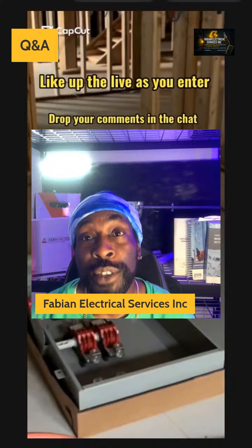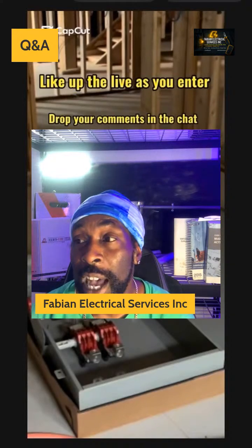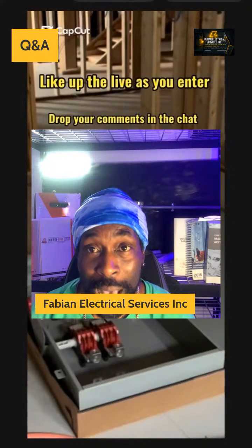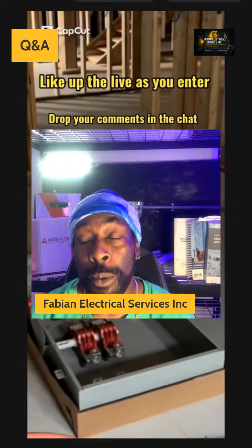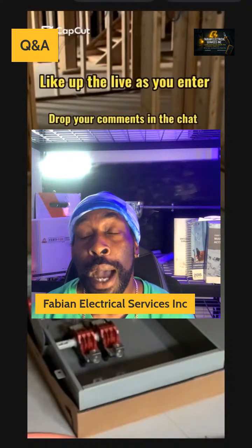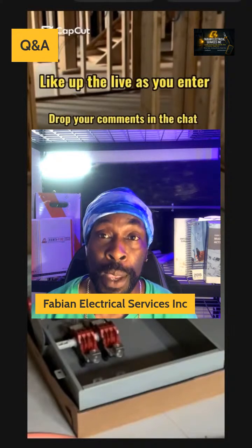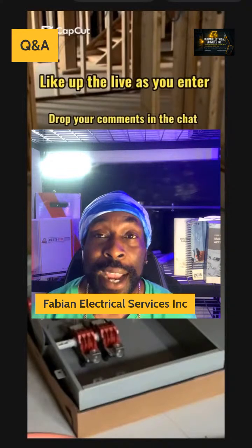If you're using T90 wire or TW75, those types of cables, you have to have sunlight resistant cable when you're doing your overhead cable and it lands outdoors where it's exposed to sunlight. So you're not going to pass your inspection just using regular cable.